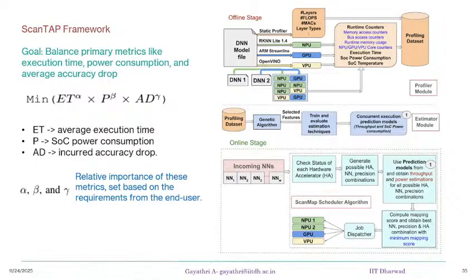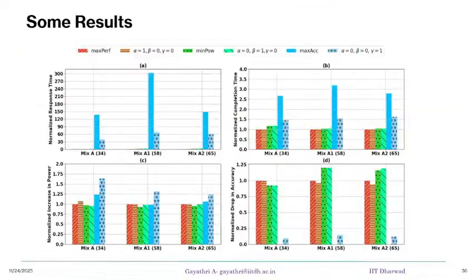Also, like I said, the SoC is very low resource, right? So if you try to handle all the hardware, all the accelerators together, you have problems with heating up and other things. So for these experiments, we tried using only two at any point of time. That is the reason you're checking the status of hardware and making sure that not more than two of the accelerators are used at any point of time. That is what this work is about.